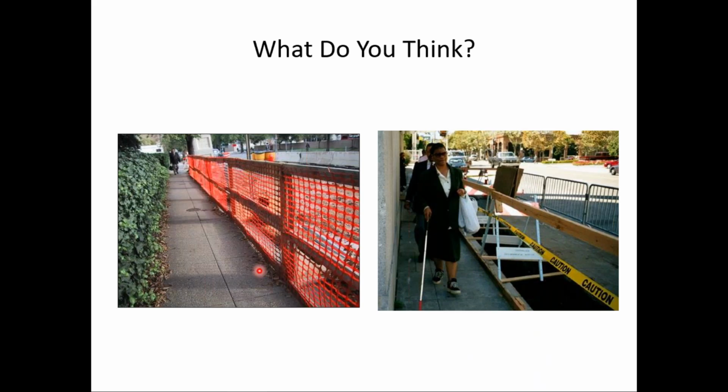How about the one on the left here? This looks like it's homemade, which is fine. And Lisa, I don't know if that's the type of snow fence you were talking about, but that's the one type I mentioned. And notice they have, looks like nailed or stapled that material to a kind of a timber frame. If this toe board or kick plate down here, if this is at least 6 inches high, which it looks like it might be, and if these are attached to each other and fixed to the ground, in my opinion, this would be a suitable detectable edging.